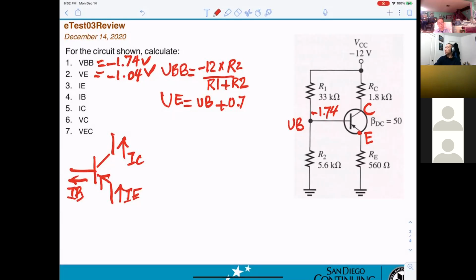Yeah, I have a question. If VCC was positive 12 volt, then we should have subtracted 0.7. Is that correct? Hold on. It cannot be positive. If it's positive, the circuitry will be different. Not this circuit. If it was positive, it'd be an NPN, not a PNP. PNP also, but different. We'll see. However, what I'm saying is for this way, for PNP, the voltage must be negative.